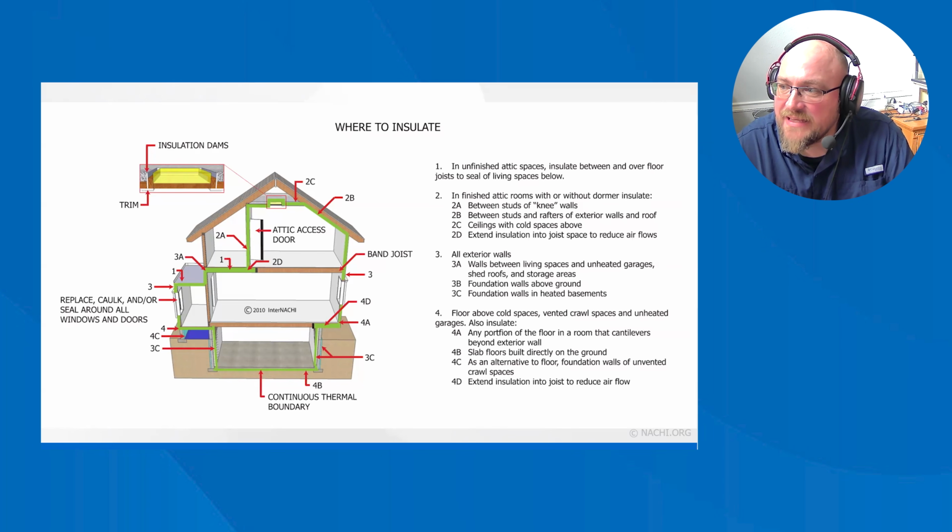It is important that the insulation is properly installed to achieve its maximum R value. Insulation in between studs in a wall does not restrict the heat flow through those studs. This heat flow is called thermal bridging. The overall R value of that wall may be different from the R value of the insulation itself.